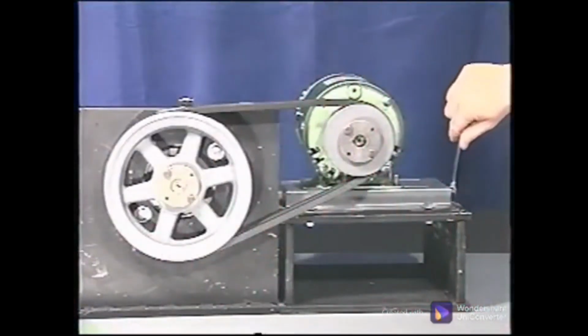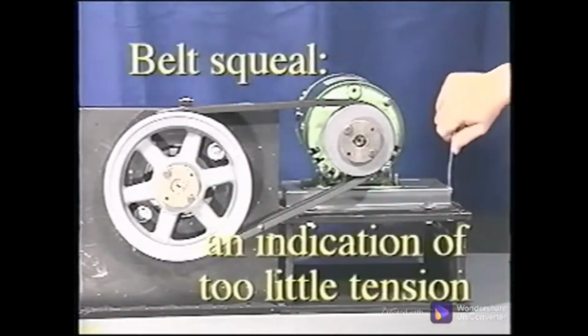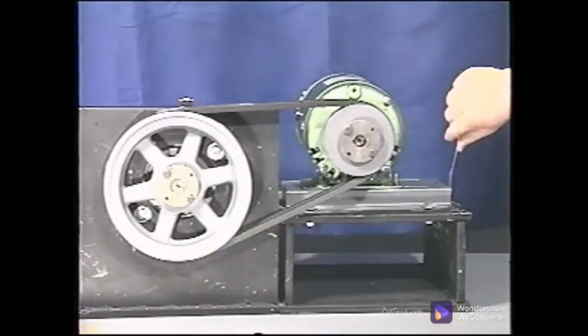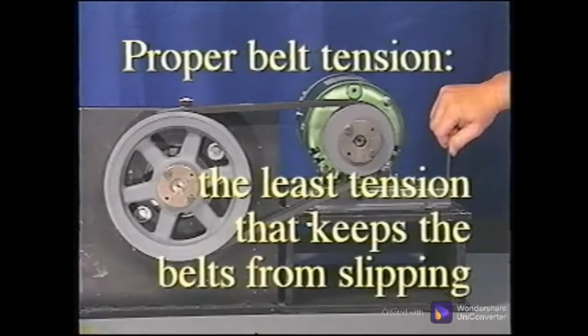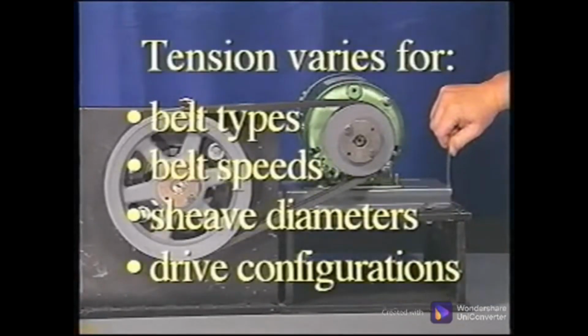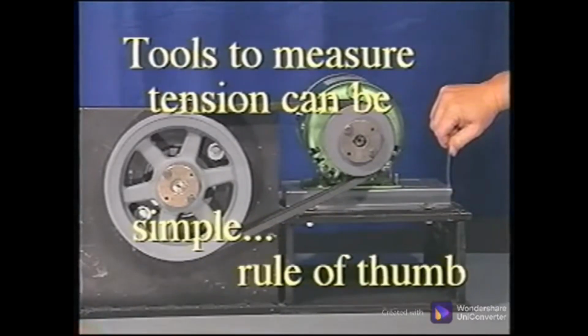Too little tension allows the belts to slip and burn. Belt squeal is an indication of too little tension. Too much tension causes separation on the outside banding, leading to belt failure. The proper belt tension is the least tension that keeps the belts from slipping. This can vary for different belt types, belt speeds, sheave diameters, and drive configuration. And the tools to measure the tension can be very sophisticated, such as an ultrasonic sensor, or very simple, such as the rule of thumb.